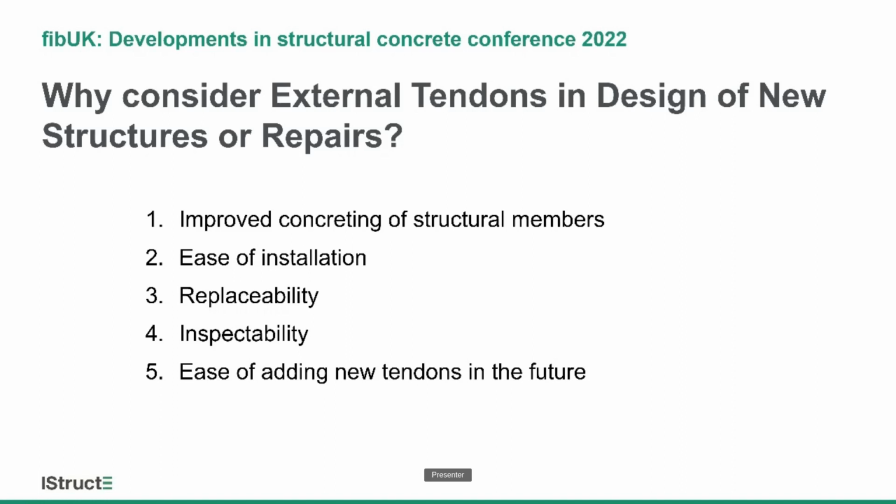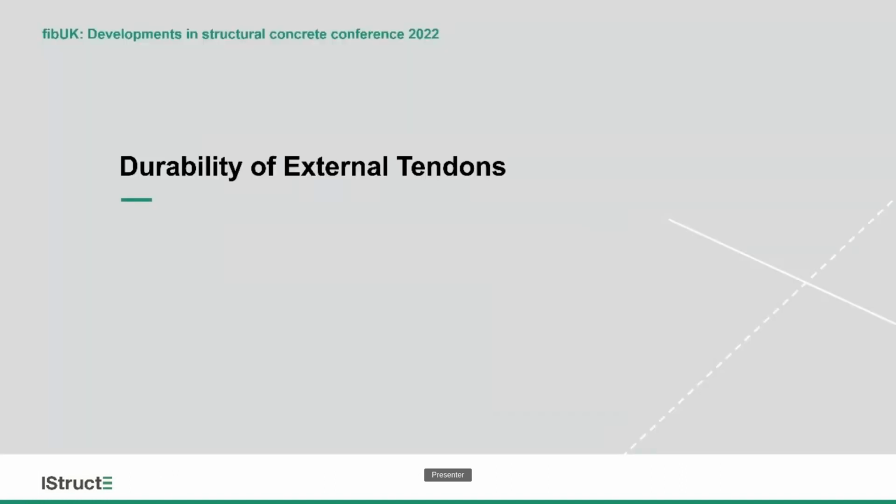So that had been a little bit the drivers why this technology was started. Originally, this started in France and in the US. The first generation of tendons typically used cementitious grout. So that was this type of tendon that I have shown you in the beginning with the PE duct, strands inside, and then the space inside the duct filled with cementitious grout.